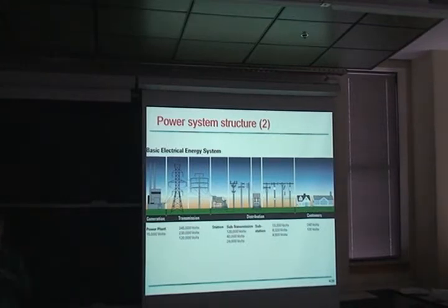So the idea is to use the existing 40 kV, kind of upload it to the 120 kV that's through there, and then there will be this new 345 that will transport it down to Detroit. And it's not far from there to Detroit anyway. Yeah, but they will be reinforced by ITC in the next year or two, or whenever they get approval.